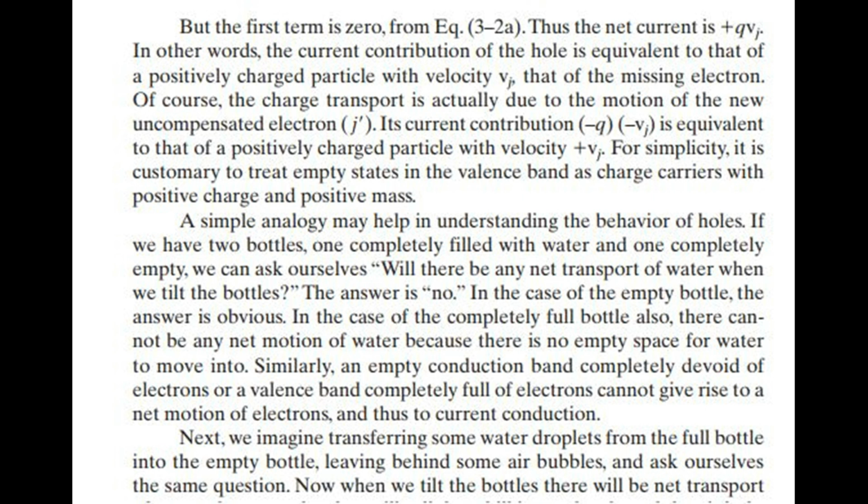For simplicity, it is customary to treat empty states in the valence band as charge carriers with positive charge and positive mass. A simple analogy may help in understanding the behavior of holes. If we have two bottles, one completely filled with water and one completely empty, we can ask ourselves, will there be any net transport of water when we tilt the bottles?